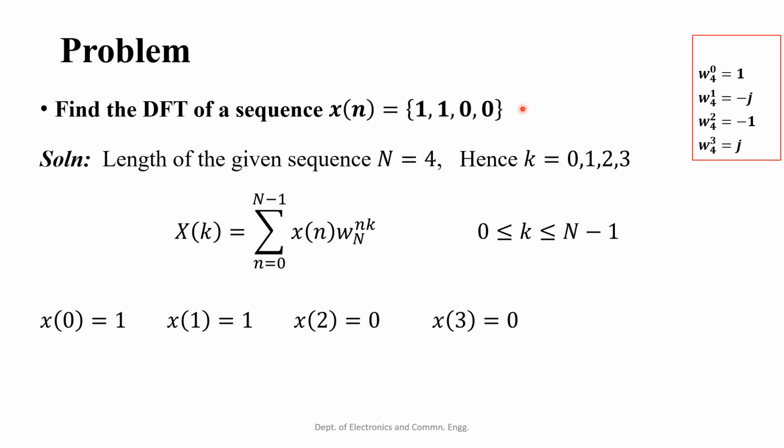I told you in the previous slide itself, we need the values of the twiddle factor. Therefore, throughout the calculation of DFT, I have put this at the side. So these values you will keep identifying as you keep solving the problems. At every DFT calculation, we need not show the calculation for this twiddle factor. You can just remember it and make the substitution while calculating the DFT.